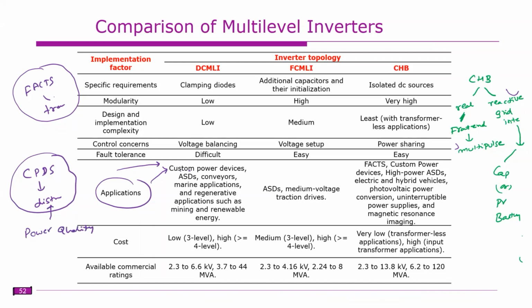It may be used to reduce current harmonics, voltage harmonics, for reactive power compensation, power factor improvement, unbalance compensation if the load or source is unbalanced, or neutral current compensation. Or if a voltage sag or voltage swell is there, all these can be compensated. So primarily it will improve the power quality. I think you might have studied the subject power quality, right?